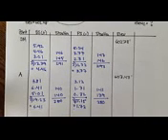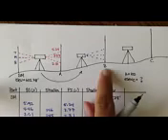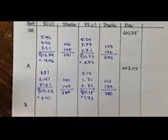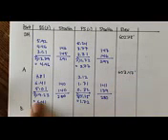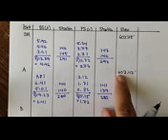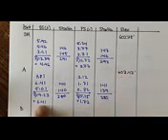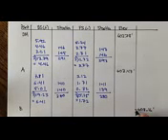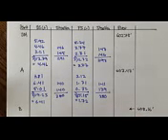Okay? So, to find the elevation of point B, you take the previous elevation, you add the backsight, and you subtract the foresight. So 603.47 plus 6.41 minus 1.72, you get an elevation of 608.16 feet. Why I wrote that in the blank column, I'm not sure. This actually goes here. Now, let's do this process one more time.